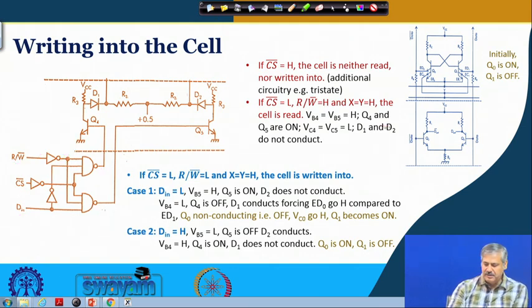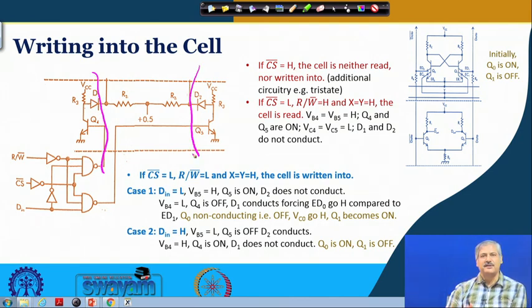Then rest of the thing is, if then this is high and this is high. So these two transistor Q4 on and Q5 on. Okay. So this voltage over here is very small. This voltage here is very small, 0.3 volt, 0.2 volt, 0.1 volt of that range. Okay, right. So then this diode is off. This diode is off. So this part of the circuit is as if it is not there.